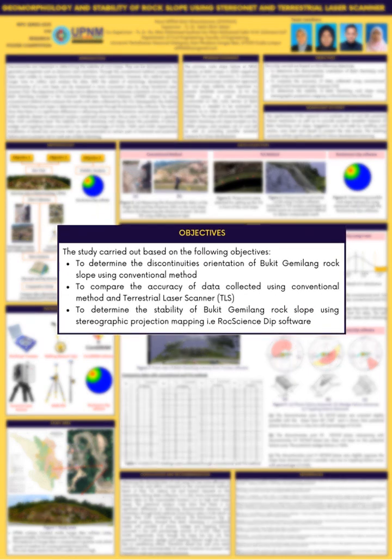First, to determine the discontinuities orientation of Bukit Gemilang rock slope using the conventional method. Second, to compare the accuracy of data collected using the conventional method and Terrestrial Laser Scanner, TLS. Third, to determine the stability of Bukit Gemilang rock slope using stereographic projection mapping, for example, RocScience Dips software.